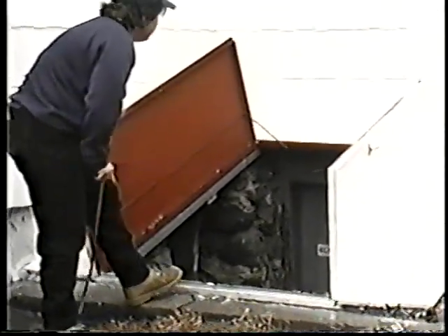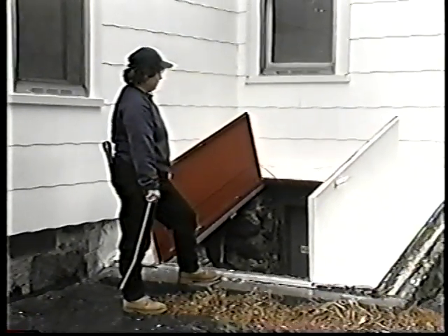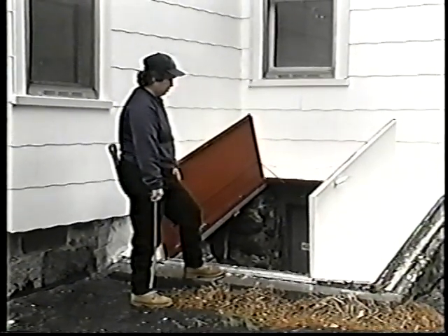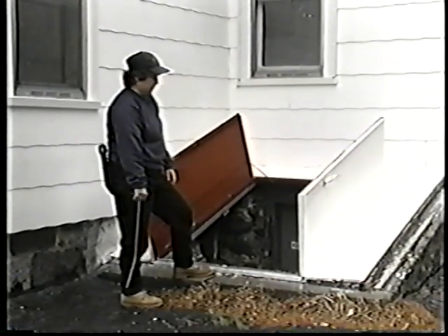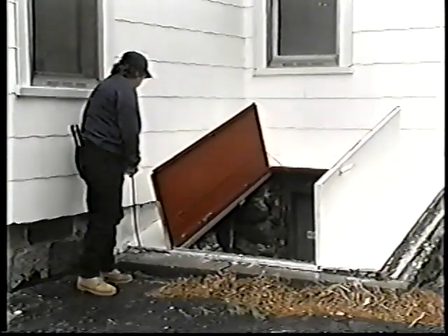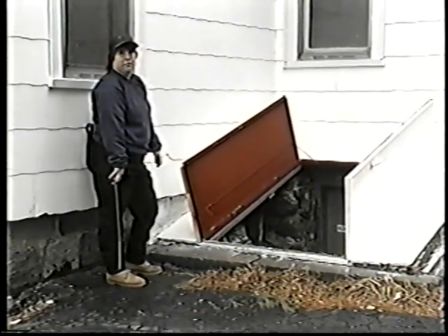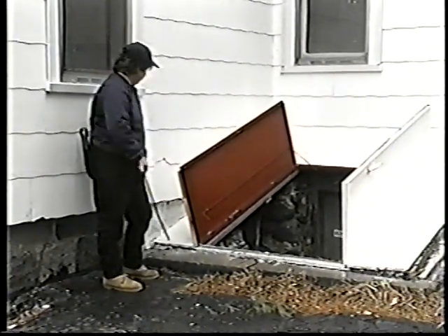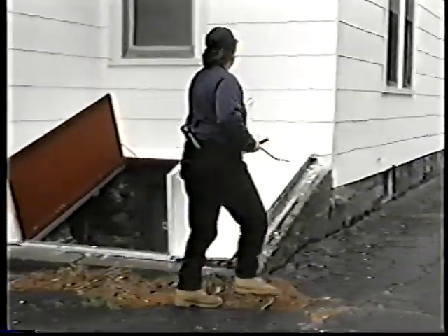On the hatchway and cellar doorways that we have up here in the east, we check all around the framing, because termites, this is a top hot spot, front porches, stoops. In Florida, if you have a porch that's attaching to the house, that's going to be a hot spot to be checked. And the crawl spaces down there will have to be looked in. I know a lot of you have them, and down there you definitely have to get someone in there and look for the mud tubes. Another spot is always where the headers meet.